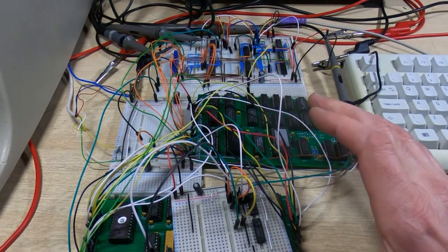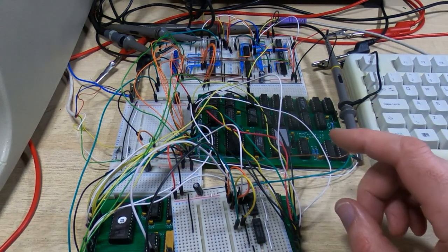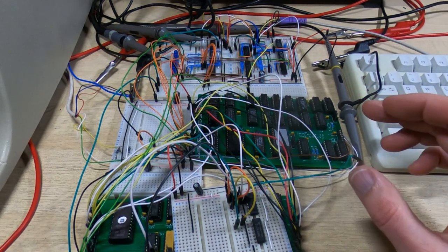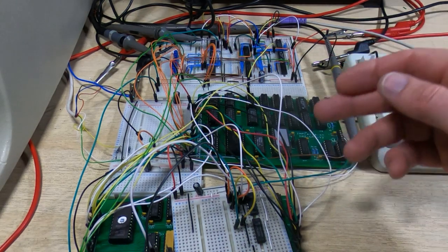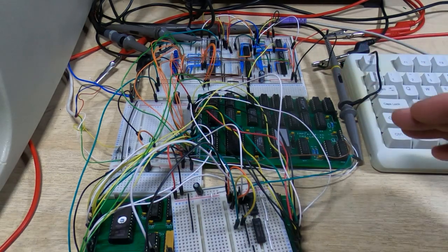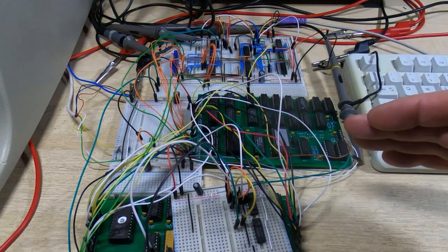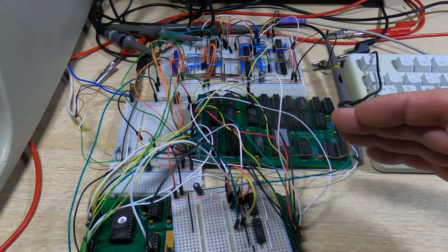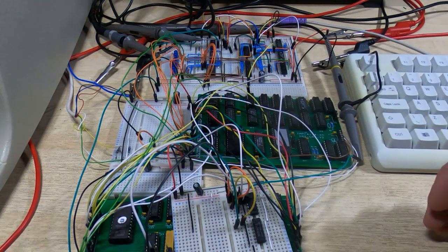So now that we can display characters on the screen and we can correctly interpret them, the next step is to create the cursor. There are many ways you can create a cursor on a design like this. You can have hardware counters and coincidence testing, so you have a couple of counters for X and Y for the cursor, and when they match the current position being scanned by the video output circuit, the cursor is created.